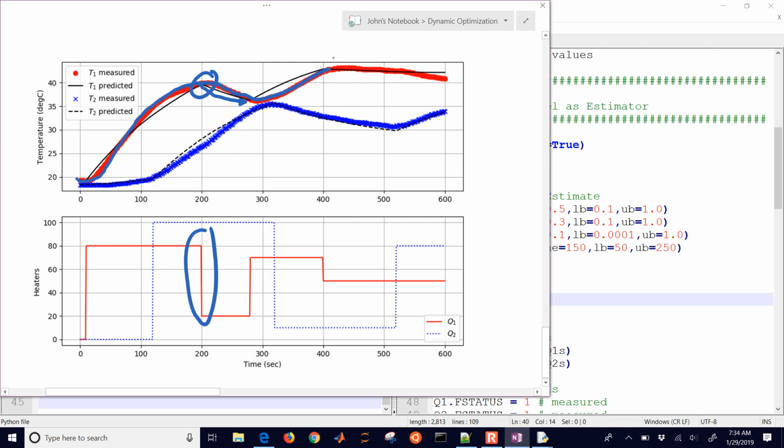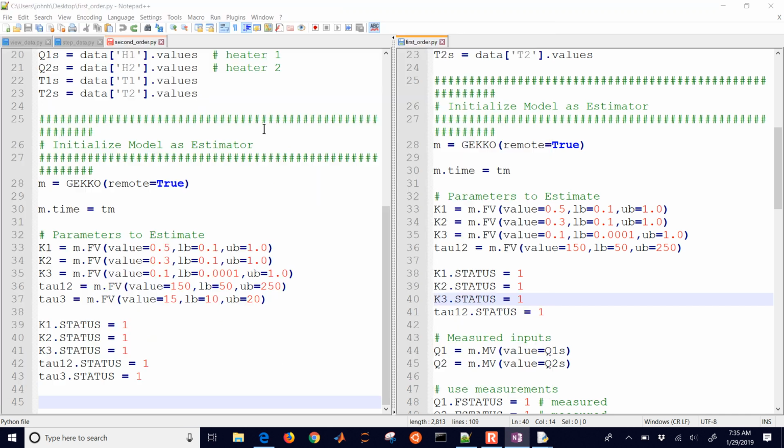It's more smooth. I think what's happening there is you have your heater and then your temperature sensor, and there's a little bit of conduction between those two. So by using a second order system, we're effectively saying, here's a temperature of our heater, and here's the temperature of our sensor. We're going to divide those into 2 zones, and let our empirical estimation track it with 2 differential equations, not just 1. If you're doing it with the 2 heater, that's going to be 4 differential equations in total.